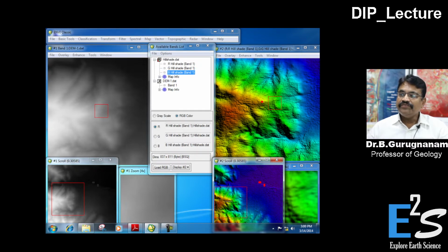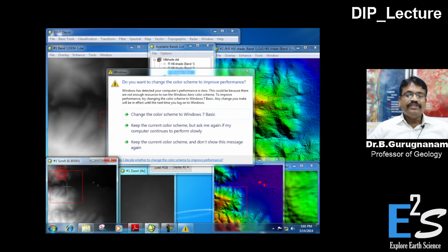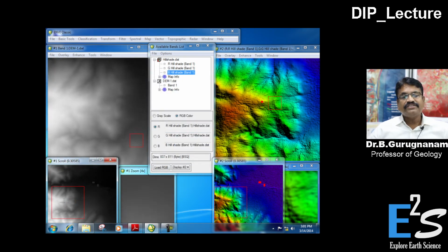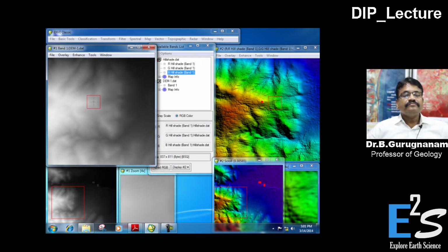You can take either a top view or a bottom view. From the top, whatever the obstacles or the slopes are, steep slopes on the other side of the view will be disabled. We will see how the system executes that. Now you see the ranges of the hills in your DEM data. Move your cursor, press and check the range at which the different elevations are represented. Look at the data.